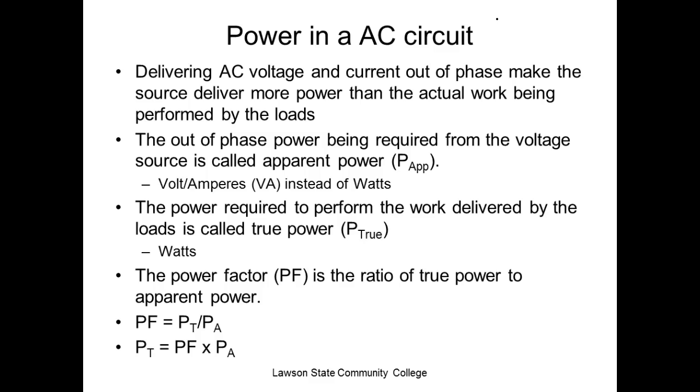So if you go out and buy a transformer, transformers are not rated in watts. Transformers will be rated in a current or a voltage. Your industrial transformers are going to be rated in VA. New motors, not the old motors, but new motors have a power factor rating on them. It's not quite the power factor, but it allows you to calculate what size capacitor you need to put in parallel with your motor to increase the power factor of the motor. But that's going to be on a new motor's nameplate, not on old ones.